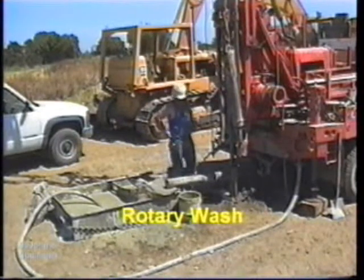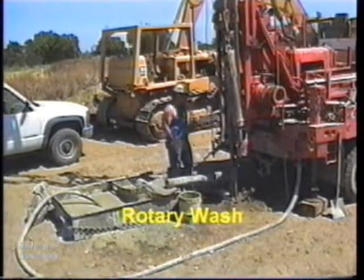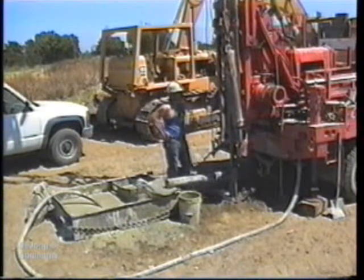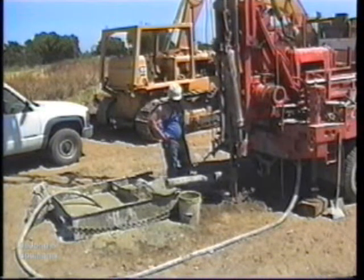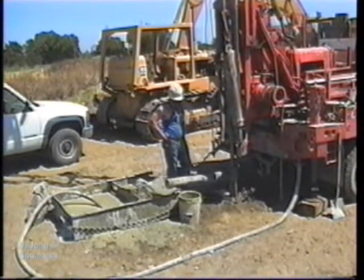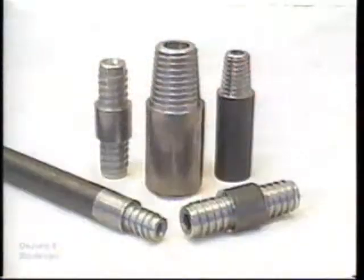Mud rotary, or rotary wash drilling, is very different from the continuous flight auger methods. The underlying principle is that mud, a mixture of water and bentonite, circulates through the borehole, bringing the soil cuttings to the surface and supporting the sides of the borehole. For drilling, a bit is connected to a series of drill rods that are attached to the drill head. Drill rods typically have an outside diameter of 1 5/16 inches to 3½ inches and are attached together using connectors like the ones shown here.